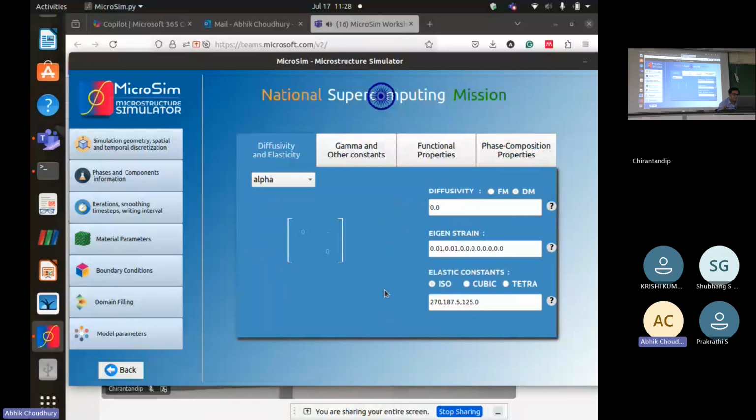And now you see the difference in the diffusivity. Instead of one value, now you have supposed to be entering 2 values. Okay, because it is a ternary alloy. So the diffusivity matrix or interdiffusivity matrix is 2 cross 2. All right. If I use a diagonal matrix, I have to enter only these 2 values. However, if I choose a full matrix, you see the other values also get to be initialized.